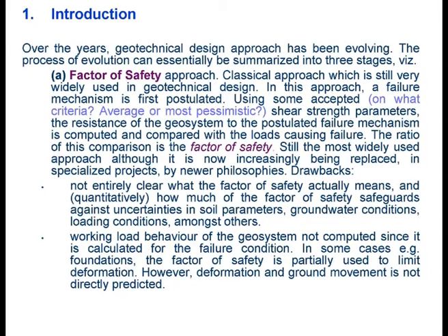And usually at the end of the day, what you want to get is stabilizing forces over overturning forces, or stabilizing forces over destabilizing forces. The number is captured in something called a factor of safety, and you need to have a certain minimum value to pass. And that minimum value can be subjected to a lot of argument.